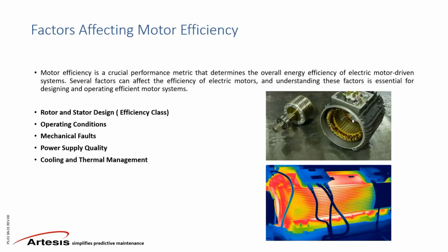And another factor here is the power supply quality. So, whether the motor is driven by a VFD or transformer, or if you have just a mains supply, the quality of the power supply will affect the performance of the motor, and of course, these factors will be the voltage quality, voltage imbalance, harmonics, how sinusoidal the output of the voltage signal that is coming to the stator is. So these will have a significant effect, again, on the efficiency, performance, as well as reliability of the motor.